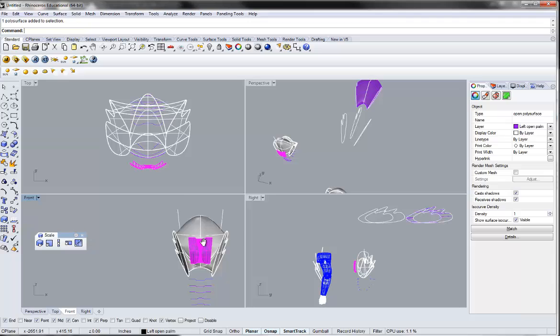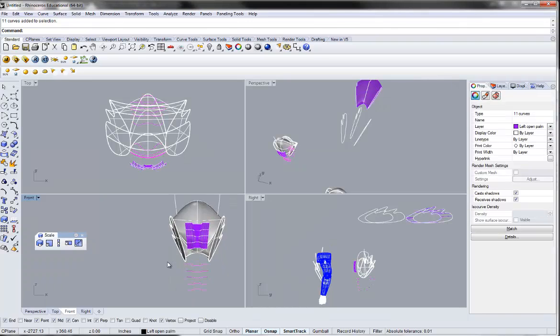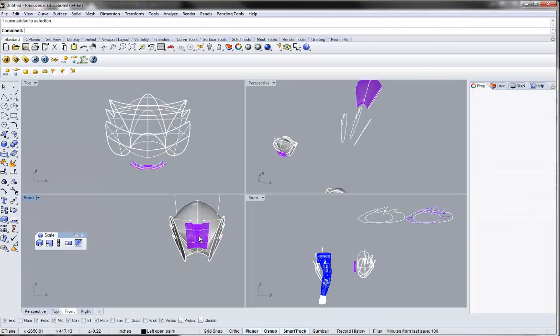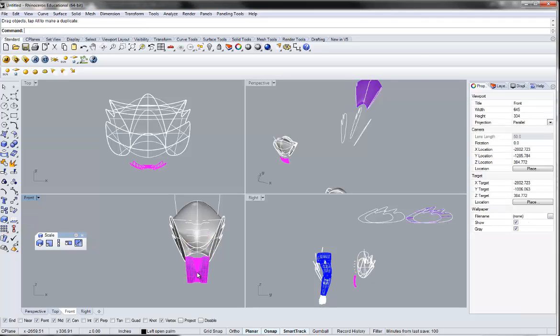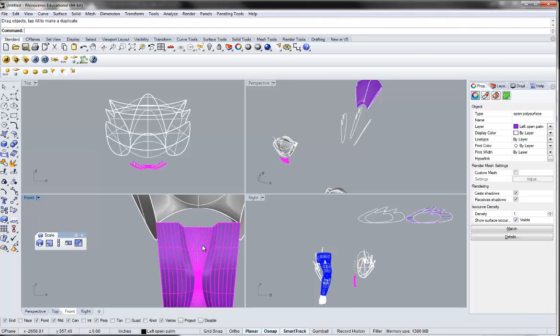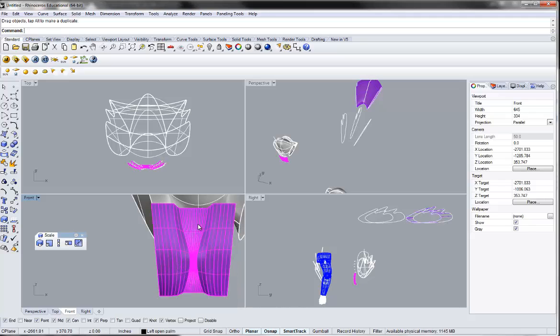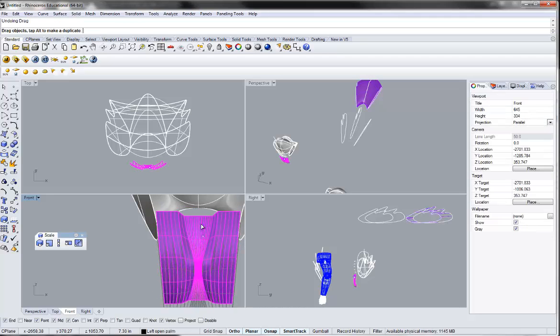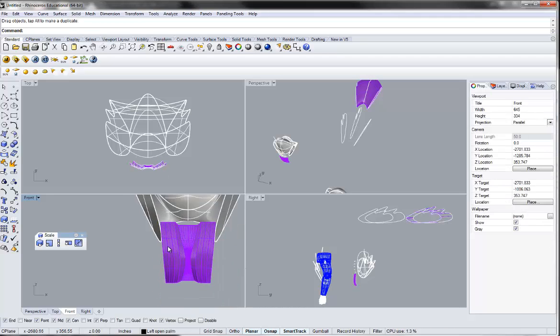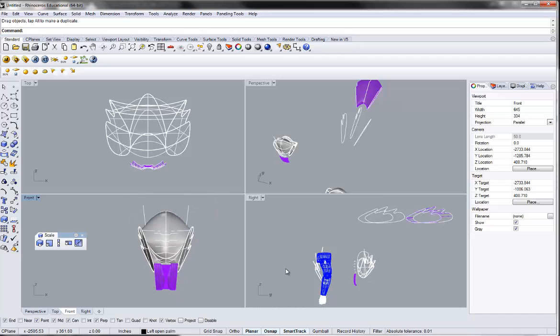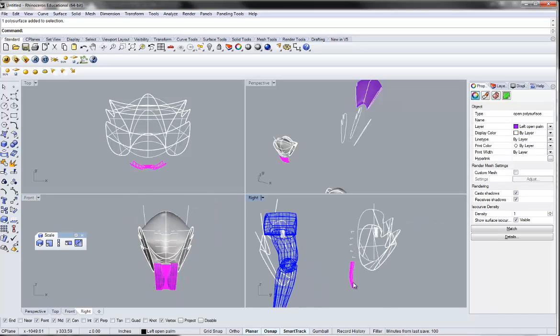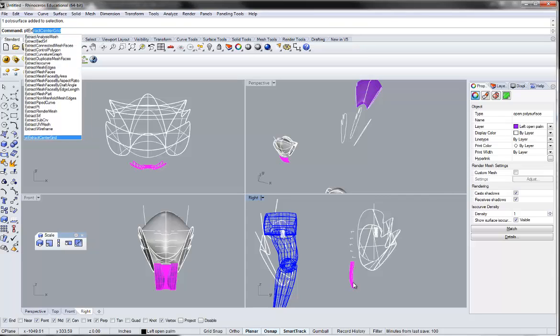And so I had this guy right here, and I'll hide the stuff that's extra now. I took a bunch of 1 degree curves to develop the section here, and then I set that in there so that I could get a little bit of opening on my abs. So this would be what the chassis would look like. And then I took that and did an extrude surface.